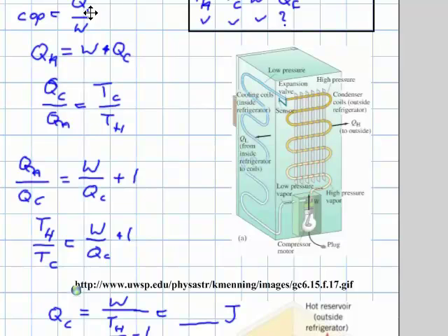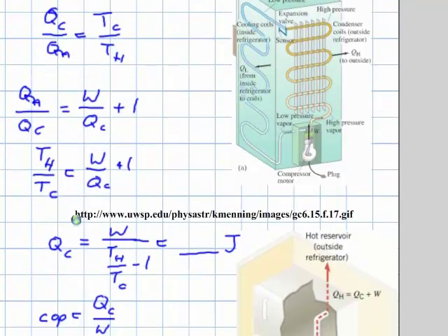And overall, we actually didn't need this equation here. The COP isn't given, and it turns out that we're not determining it during the overall problem. However, if I was to determine this, and let's assume that I already know what the QC is that is being calculated here and divide by the 2,500 joules, I come out with a coefficient of performance of about 15.